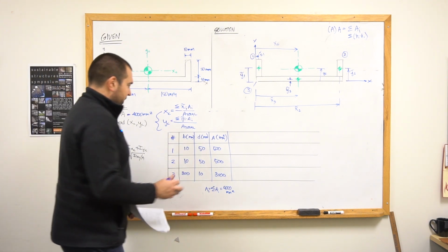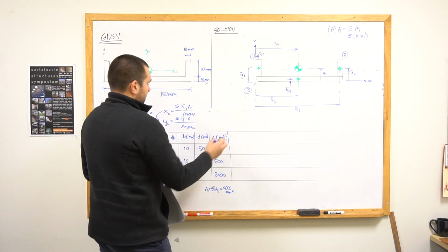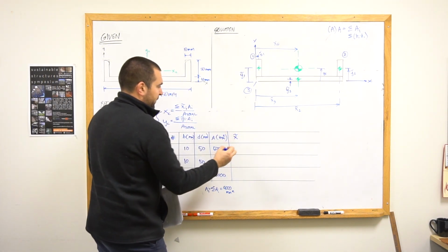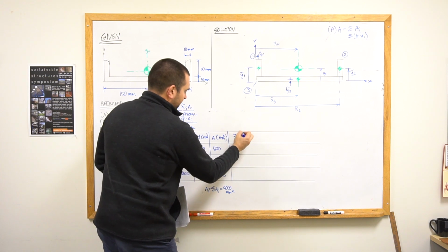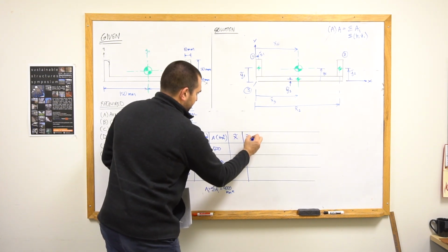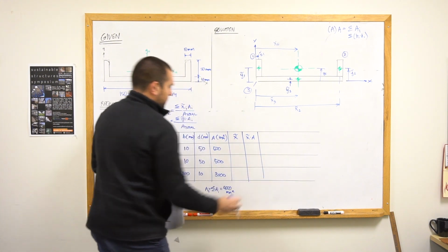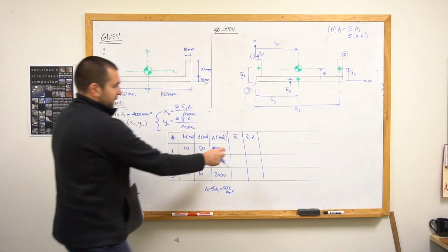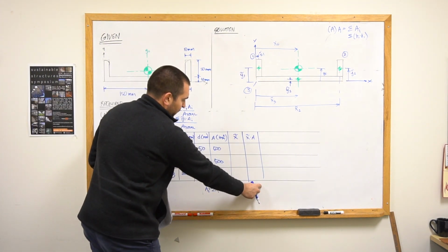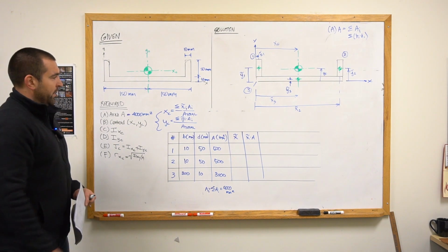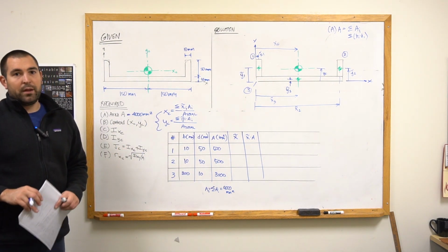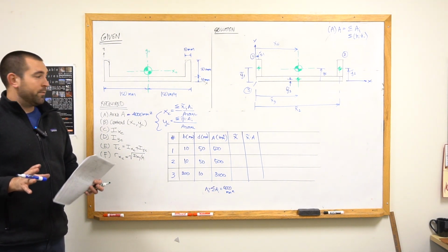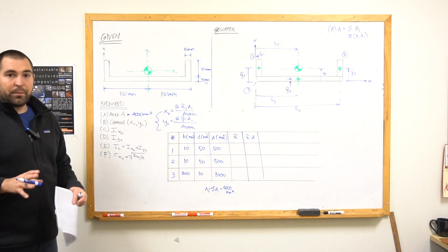So what's going to make sense here is if I were to tabulate the x tilde values, and calculate the x tilde times A values as well, that's going to be the way to figure it out. Because I can simply sum up everything in this column right here, divide by the total area, and that's going to give me x sub c. Now, the calculation will give you the correct answer. It's just a little bit of work. It's all simply algebra, not a big deal.